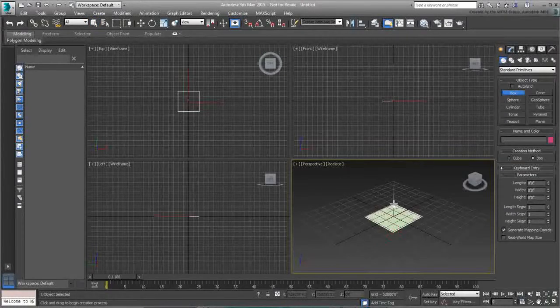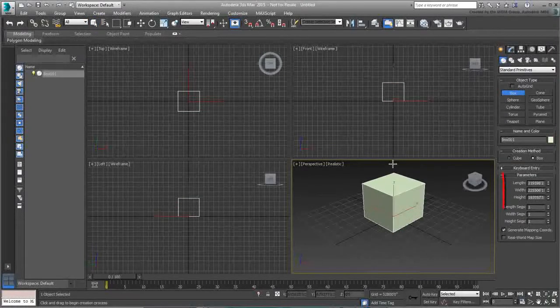the box is now insanely big, over 200,000 feet in each direction. Unless you are working on huge expanses of terrain, you may want to avoid setting system units to such a large scale. So keep that in mind and set your system units to match the general scale of the project you are starting.